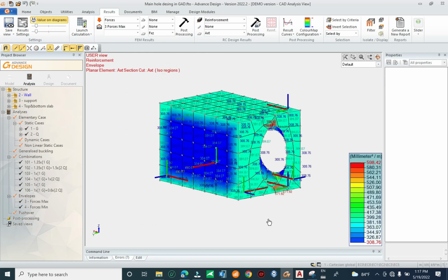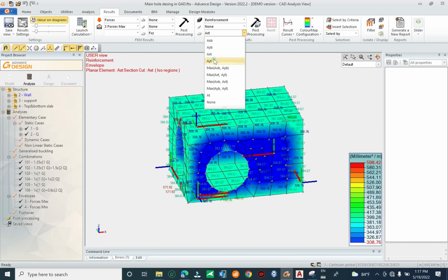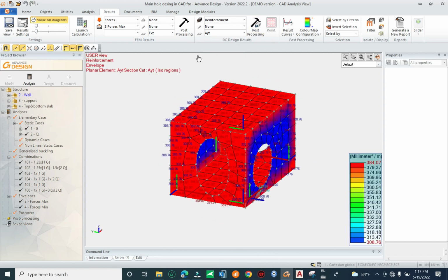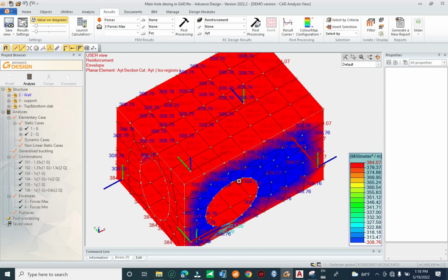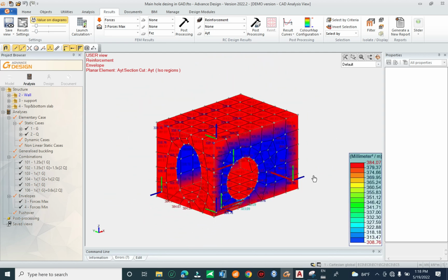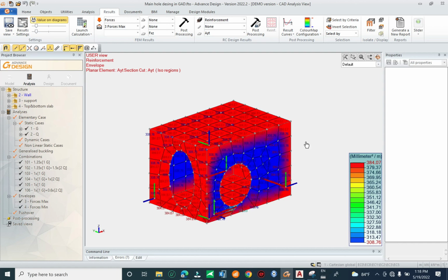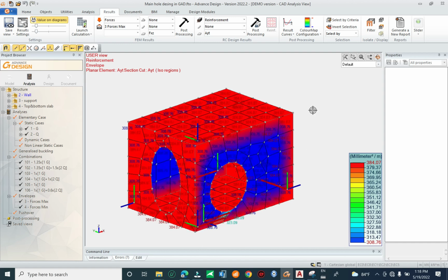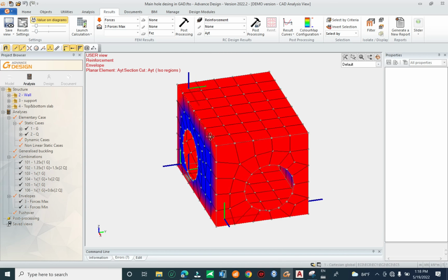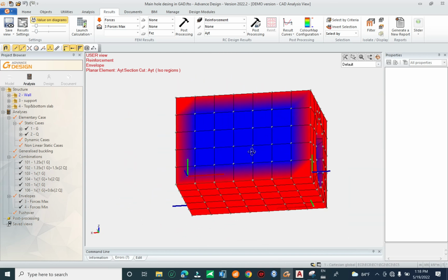Okay, you can check for all the loads and outside, and rebar in each direction at the top layer. Okay, you can check here. The maximum is 384. Maybe this is the minimum rebar in the section. You can verify the minimum rebar in the section to compare for this section how much rebar is required for the minimum to prevent cracking appearing in the section.